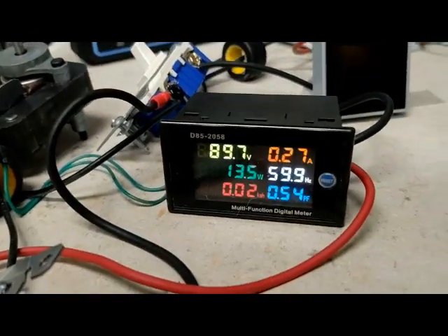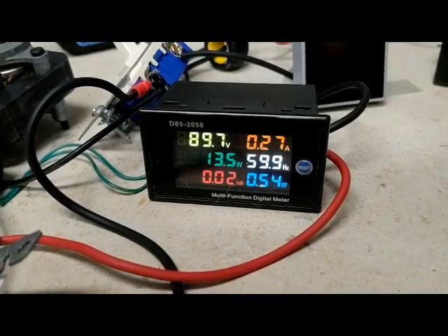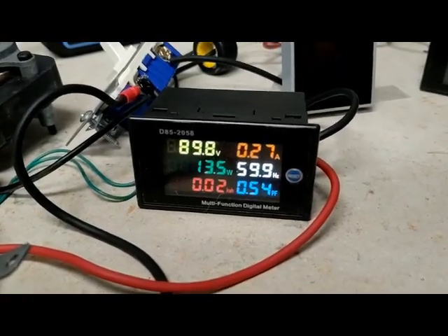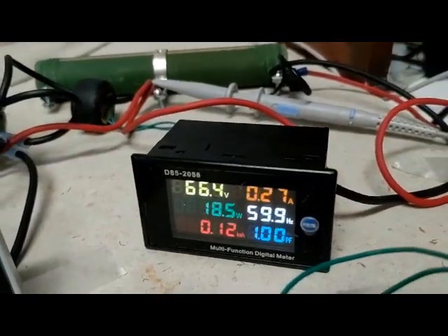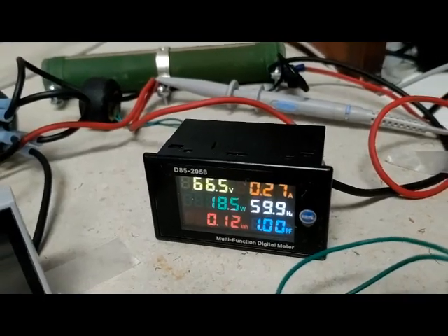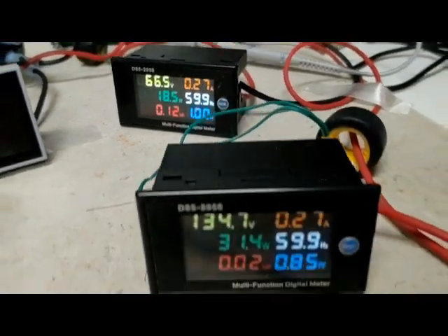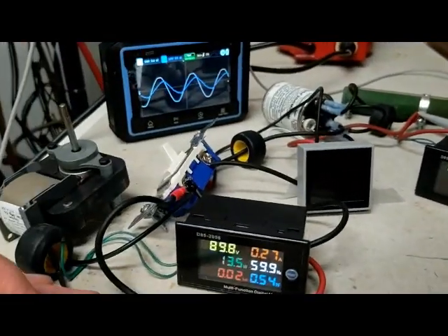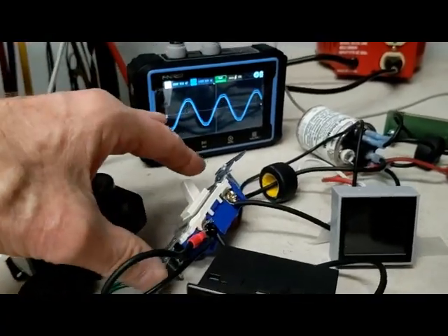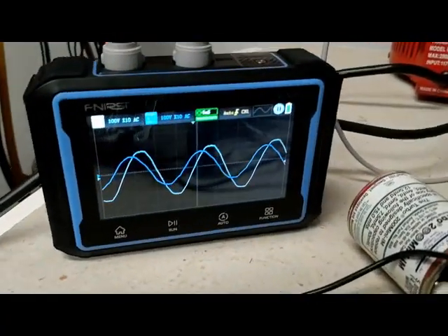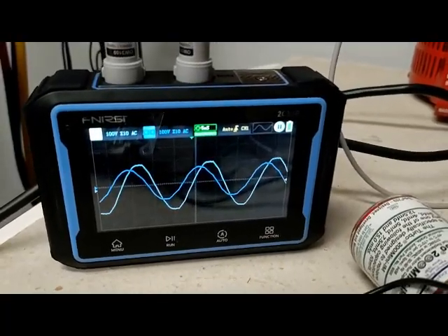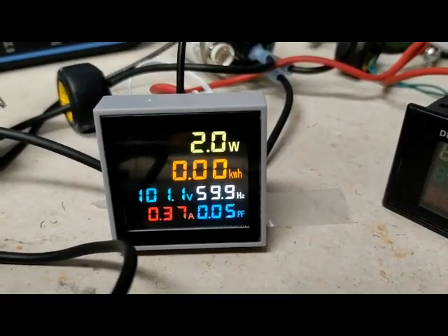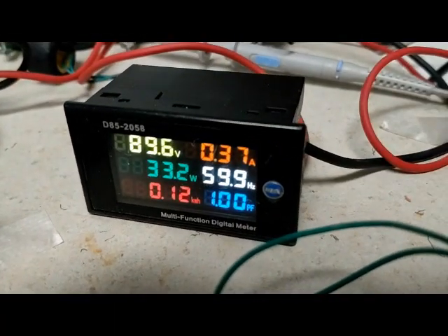The power factor for the little fan is about 0.5, and it's receiving about 90 volts. Power factor for the resistor is still 1, but the voltage it's getting has dropped to around 67, and you see the voltage coming into the circuit still pretty much the same. Now I'm going to take the motor back out and bring the capacitor in, and now you see the current leads the voltage. The capacitor is getting 101 volts, while the resistor is around 90.